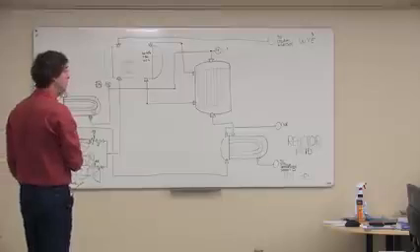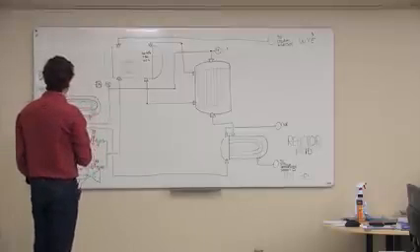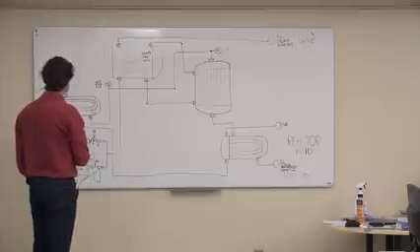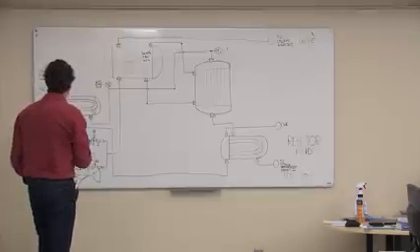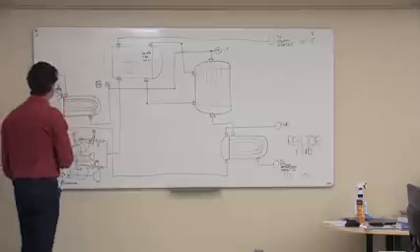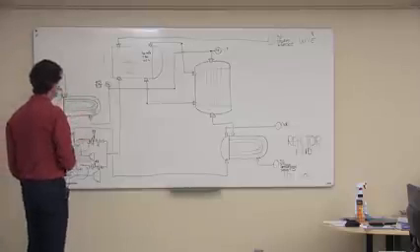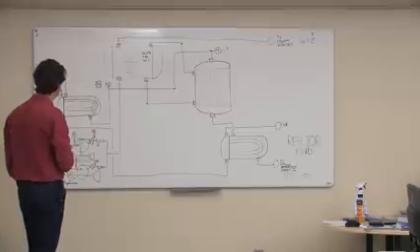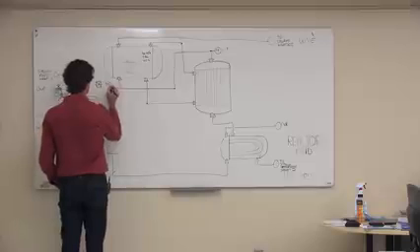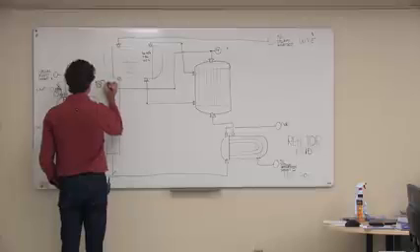So there's a simple single input, single output control loop. You might want to give the valve an instrument balloon. Because it's on temperature control, it's basically a temperature valve. And we might be concerned with whether that temperature gets high or low. So we'll put a temperature alarm high and a temperature alarm low in there.